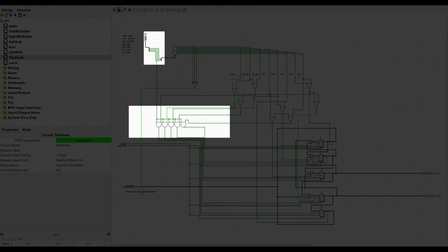In this way, whatever is on the op side, whatever the command is, whatever the other 3 bits are, and whatever the decoder selects, if I don't have the 4th bit enabled, all the write enables are gated and no update happens. And that's it. I already did manual checking, it works, but I probably need a proper test bench.